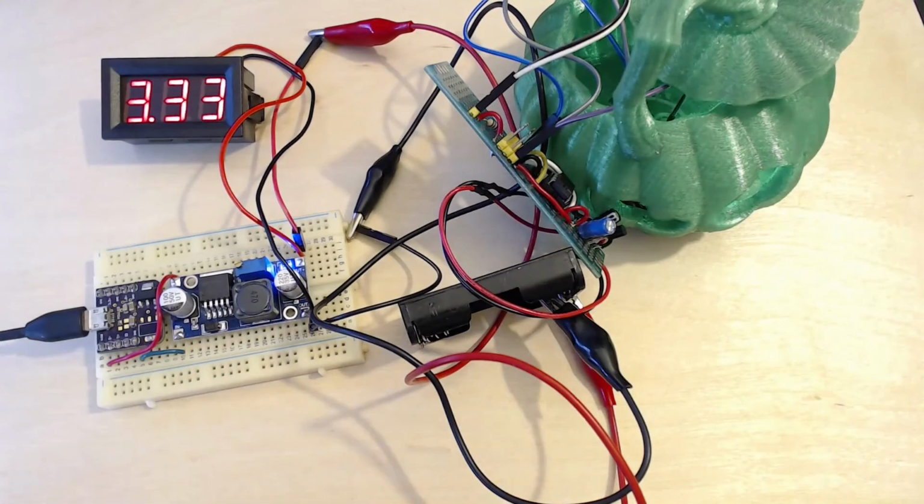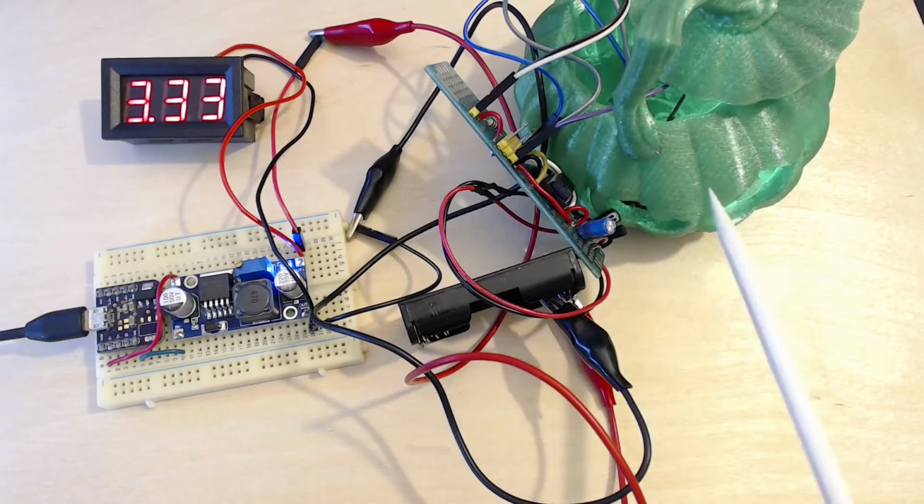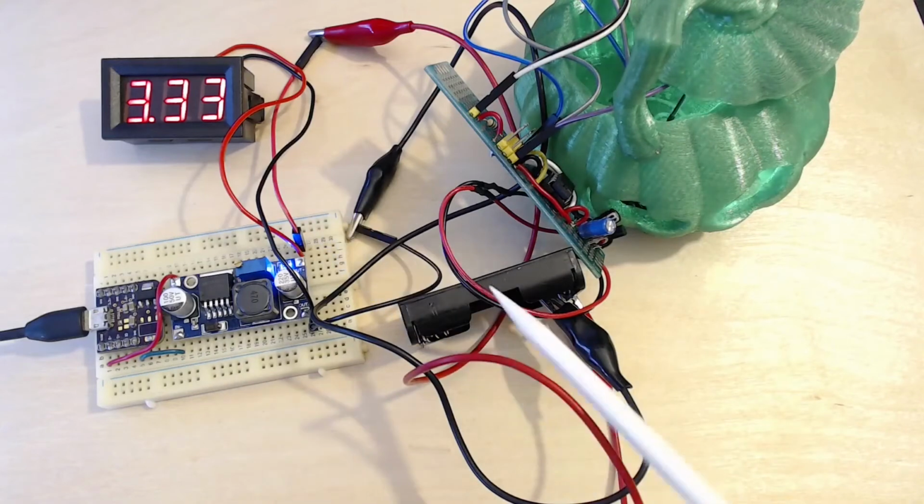The reason for that is we have our 3.3 volts here coming to our circuit board, but our LDO is also dropping around 0.2, 0.3 volts. So it's about 3 volts, and now our motion sensor stops working. It's unable to pull the motion sense line down. That's why just the light keeps glowing, and it makes the situation worse because this happens when the batteries are